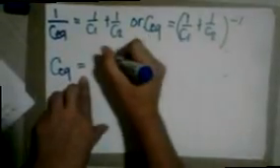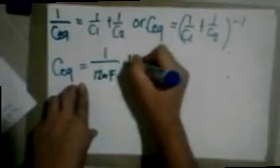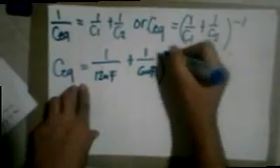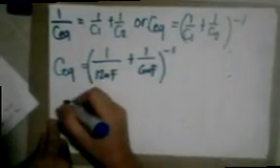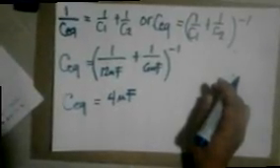So C equivalent equals (1 over 12 microfarad plus 1 over 6 microfarad) inverse, and our C equivalent is 4 microfarad. Since we combined the 12 microfarad and 6 microfarad capacitors and the equivalent capacitance is 4 microfarad, our reduced network would look like this.